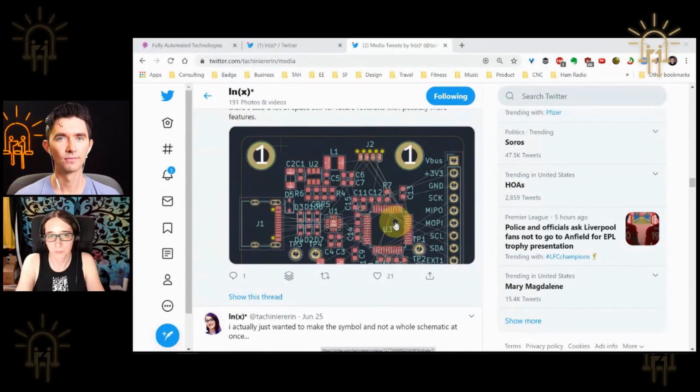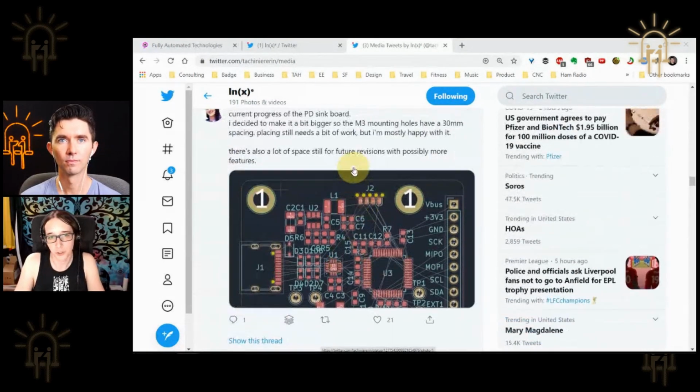Also to have it so that it's not too crowded. Split it up in functional parts so that, for instance, if it's a more complex power supply, you keep the power supply in one part, and the microcontrollers and control stuff on different sheets. So when you're debugging something, you really have the thing you're working on right in front of you. That helps a lot for me personally.